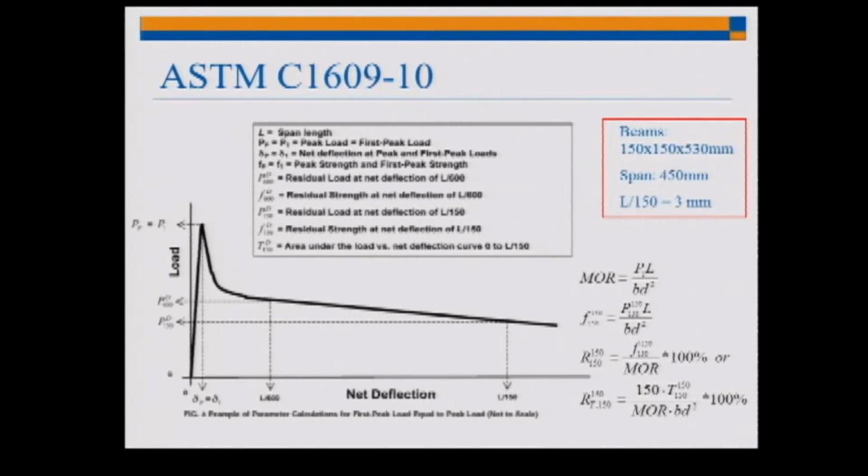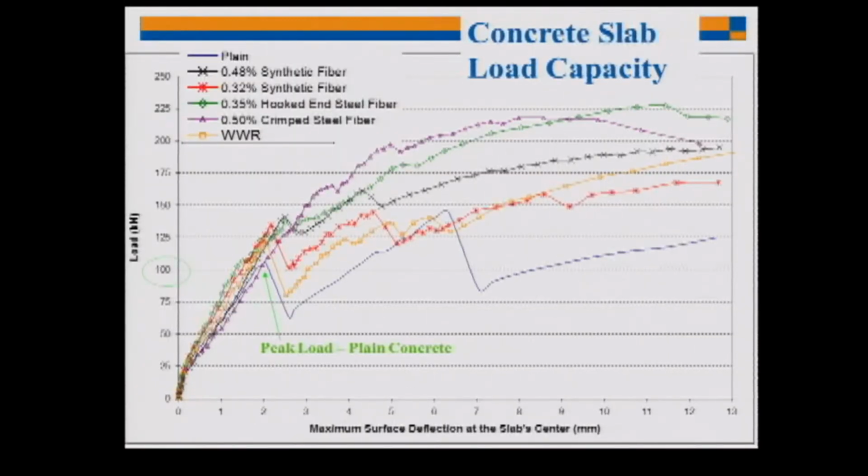So fibers are kind of designed to work for certain applications. So you have to do your research on which are the best fibers to use. Now, this is the important part. I said that when I add fibers to concrete, they don't increase its tensile strength. But when we add fibers and we test a slab, and these are slab tests, so I put fibers in a concrete slab and then I test it, I load it, it increases the cracking strength of the slab.